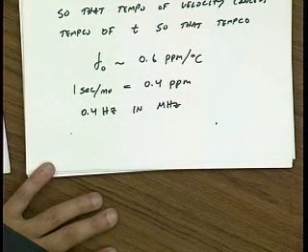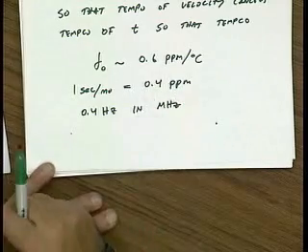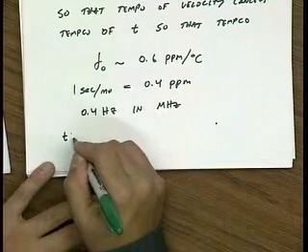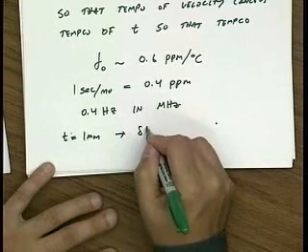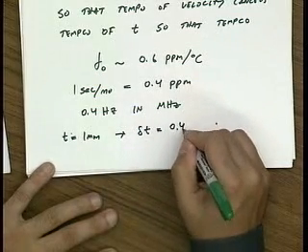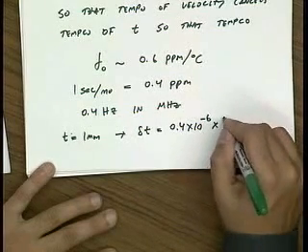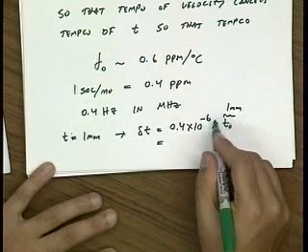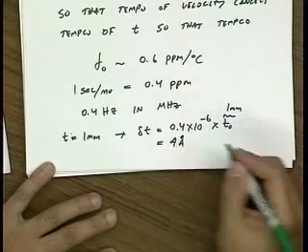Let me give you another way of looking at that stability. It's interesting to translate this 0.4 ppm stability into just a change in thickness. So if I have a 1 millimeter thick material, delta T would be 0.4 parts per million times T naught, which is 1 millimeter, so T naught is 10 to the minus 3, times 0.4 times 10 to the minus 6, so it's 4 times 10 to the minus 10, or just 4 angstroms.